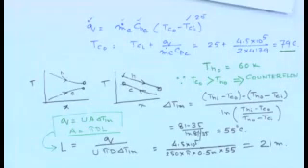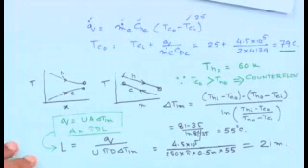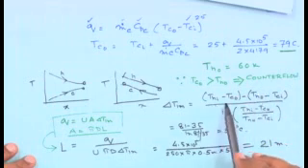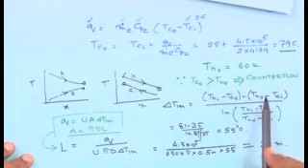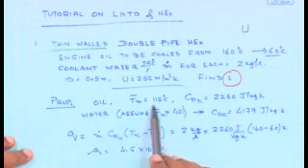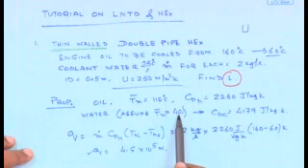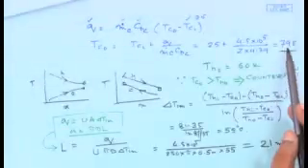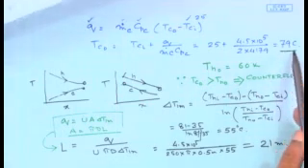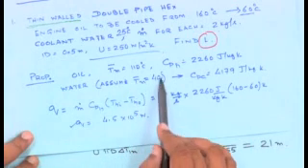So we have seen a couple of considerations while solving this problem. One, very important, is you need to find out whether it's parallel flow or counter flow and calculate the delta T Lm based on whether it's parallel or counter flow. And second, all the properties are to be evaluated at the mean temperature. I have assumed the mean temperature to be 40, and when I calculate the temperature of TCO as about 80, I see that I exceed my assumed mean temperature to some extent.